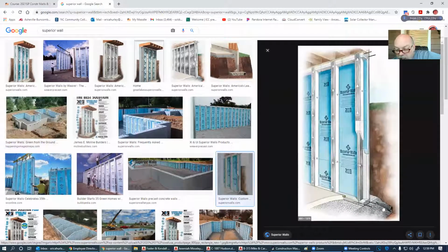Now, look at the footing that it's sitting on. These are designed with rebar in them, and again, they're made in pristine conditions with rebar all through them. Then they don't need a concrete footing. You actually can put down a gravel base footing and set these directly onto it. And when you pour your concrete up to it, again, you've got to allow for this to float, or this to move up and down, and this to stay stationary.